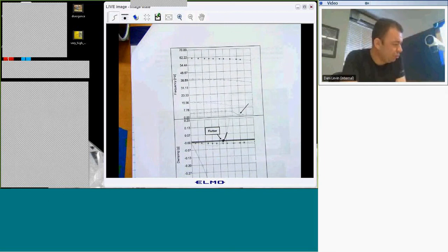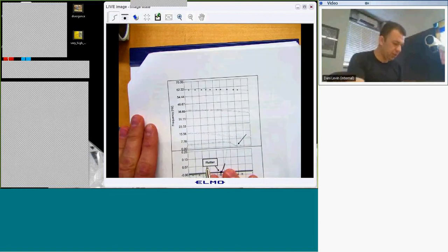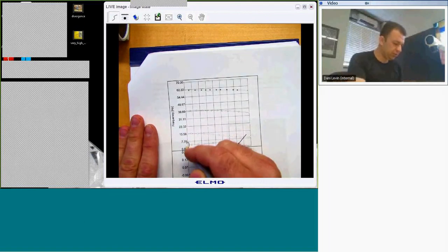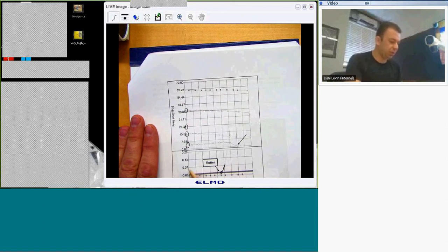Actually, when you do modal analysis in ANSYS or in any software, for that matter, it automatically assumes that the right hand of your equation is zero. So no matter what you add as your load, it will not consider it. For the other part of this question, if you look at this graph, these are my results of the modal analysis. These are the frequencies at zero velocity.